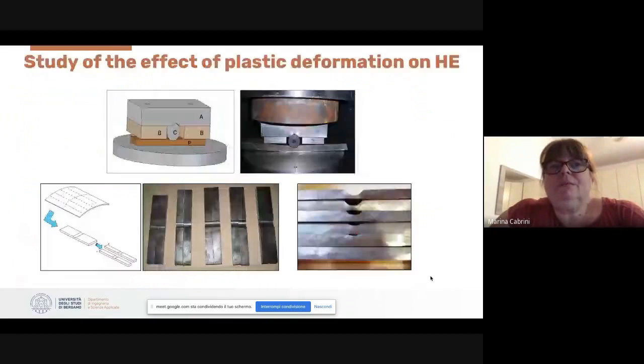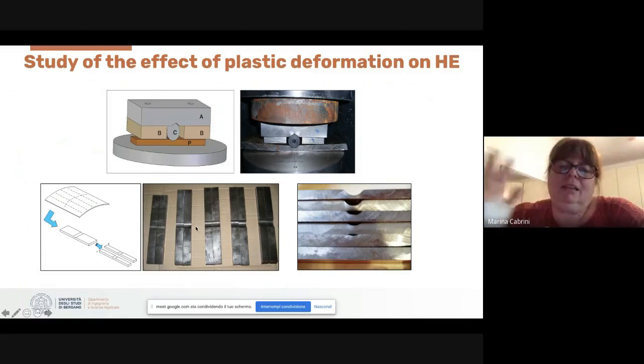For this reason, we have done some tests using a small, simple geometry of defect obtained by simple compression, using different depths of compression in order to have different straining of the specimen. We made this defect on a part of pipe, and this part was divided in two specimens, one tested in air and the other in the presence of hydrogen.